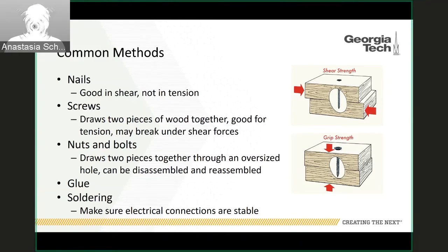On the other hand, a screw is great. It draws two pieces of wood together, so it's really good for keeping together pieces of wood that are being held in tension. If the material is under shear, you may see the screw snap, although it's probably unlikely for the forces that you'll be experiencing in this class.